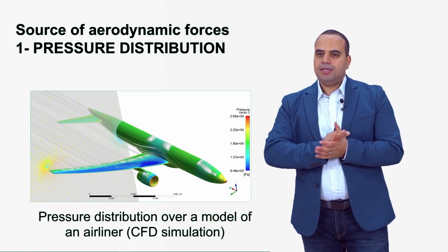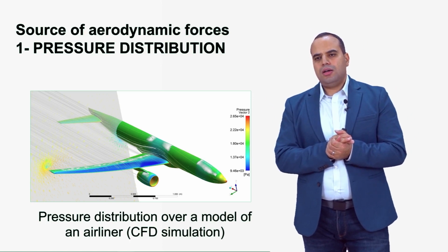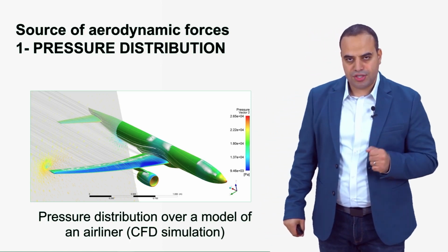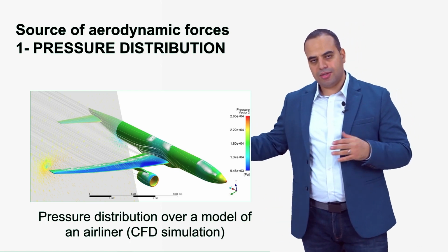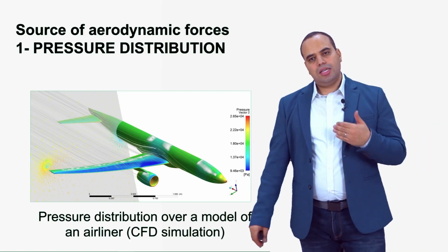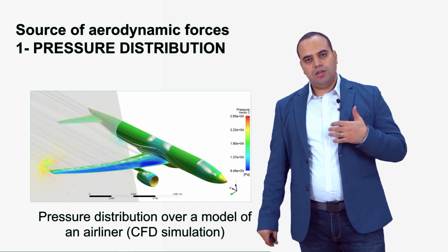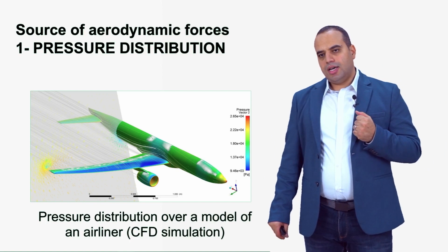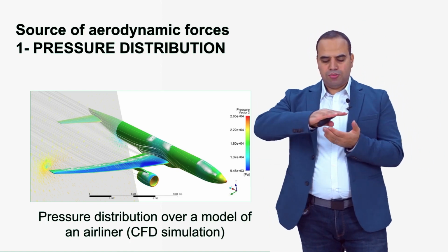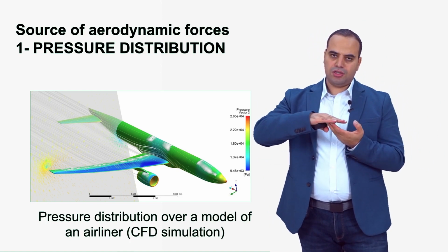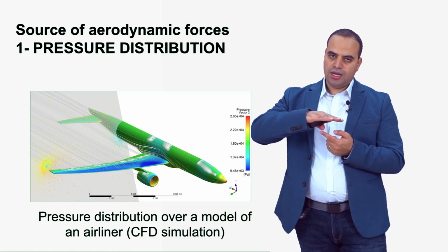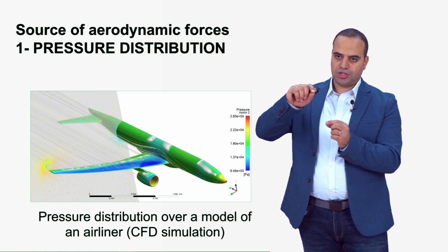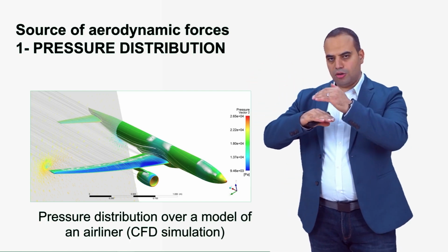Now, why is this bad? It is because this part of the wing that is attached to the fuselage is not going to be generating lift as efficiently as it would if there is nothing there, right? If it was just a clean wing, then in that case, the low pressure is going to have the maximum values possible, right? And because we have the fuselage, the high pressure beneath the wing is going to be first transferred to the fuselage, and then the fuselage will have different pressure. It will have a high pressure beneath and a low pressure from the top.